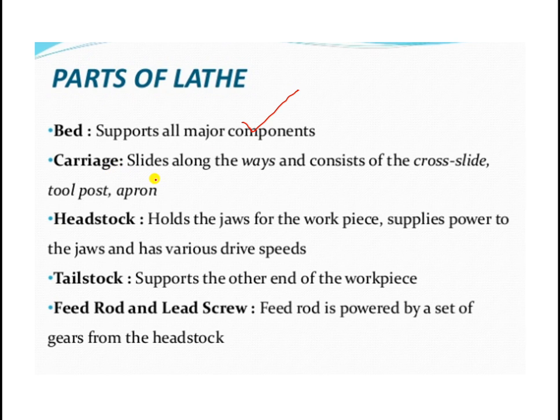Carriage assembly, which will slide along the ways in the horizontal direction like this, and with the help of the cross slide and compound rest, you can move this in the transverse direction. This is longitudinal, this is transverse. The headstock holds the jaws for the workpiece.